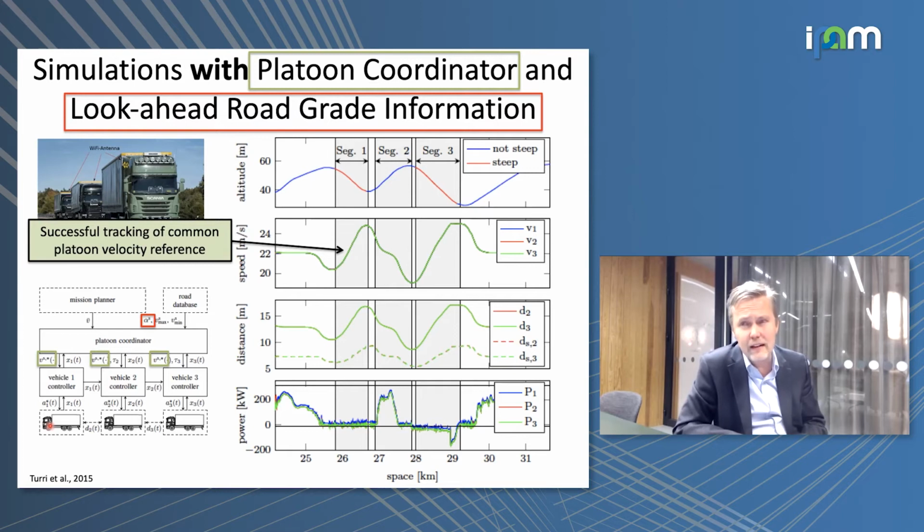But what happens in practice is that those trucks today are already fairly automated. So what is typical, if one studies how the driver drives on the highway, you anyhow run a cruise controller. So typically the first vehicle is not keeping constant velocity, but a velocity which is now good for the whole platoon. So you can compute an optimal reference velocity also there now, taking into account all the vehicles, and then you would implement that in the cruise controller of the first vehicle.